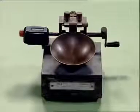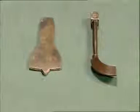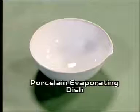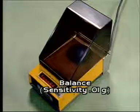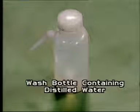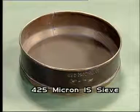The apparatus required for conducting this practical include a mechanical liquid limit device, grooving tools like Casagrande type and ASTM type tool, porcelain evaporating dish, spatula, balance with sensitivity to 0.1 gram, thermostatically controlled oven, wash bottle containing distilled water, sample containers and 425 micron IS sieve.